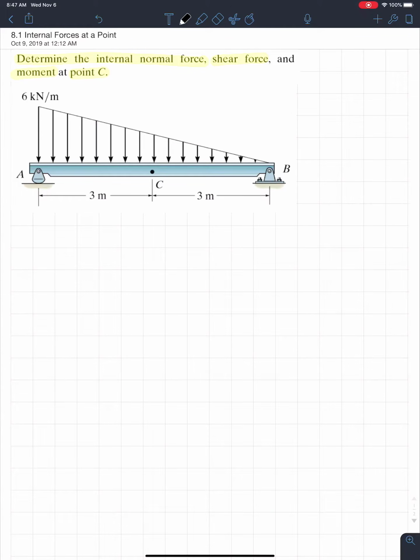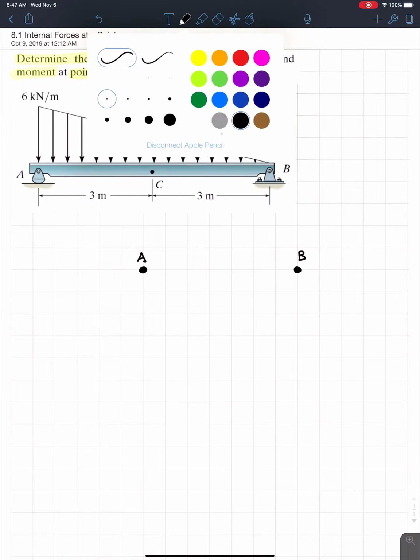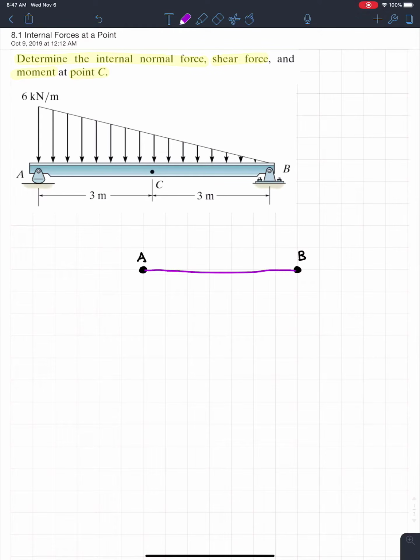So when we had a truss and we had two members, so let's say we had joint A and we had joint B right here. No matter which method you do, we relied on cutting those members. So let's say our member is this purple thing that goes between these two. And when we're trying to analyze the force in that member, so if we're trying to find out if it's, say, 100 kilonewtons in compression or 300 kilonewtons in tension, what we would do is we'd cut through the member like this. And this applies to the method of joints and the method of sections.